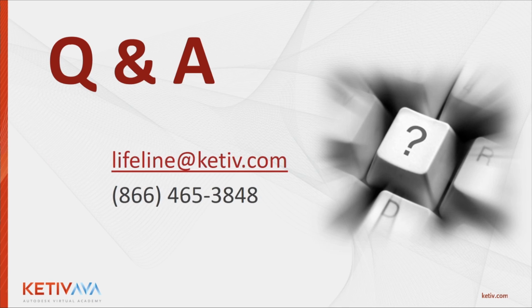I've got some related questions here. So one is iLogic rules, are they possible within the tube and pipe environment? That's one. And then two, can you use content center parts? Can you pull things like angles and channels for iLogic and use for assemblies and stuff? I know that second one is true. You can call for things in content center. But that first one, I'm not 100% sure if you want to answer that one for us, for Thomas, in regards to tube and pipe. Oh yeah, I can answer it.